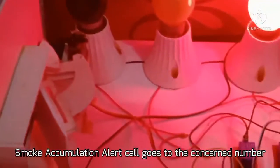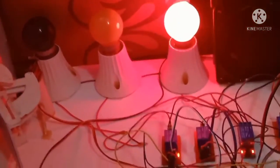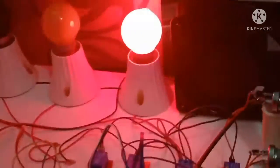The servo motor has rotated 90 degrees and the associated hinge system has opened the window. Also, a smoke accumulation alert call has gone to the concerned number, informing them of the mishap, and a high-pitched buzzer alarming sound can be heard. Currently, we have set the delay to 20 seconds and it hangs up after that. It can be prolonged as required by changing the code.